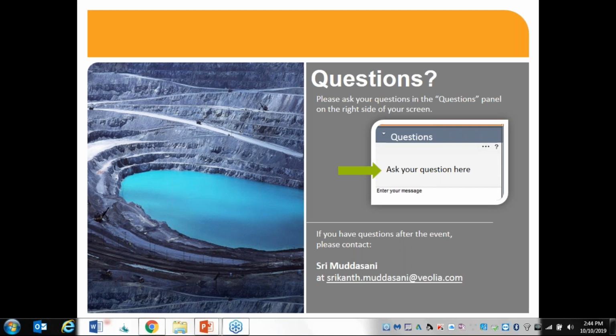Another question that came in is, what pH does the aluminum hydroxide regeneration tank operate at? That's a very, very good question. Aluminum hydroxide solubility is low at a pH of 6.5 to 7. So when you add acid, we reduce the pH all the way from 11.8 down to 6.5 to produce aluminum hydroxide. And the optimum pH, I would say, is 6.5 to 7.2.